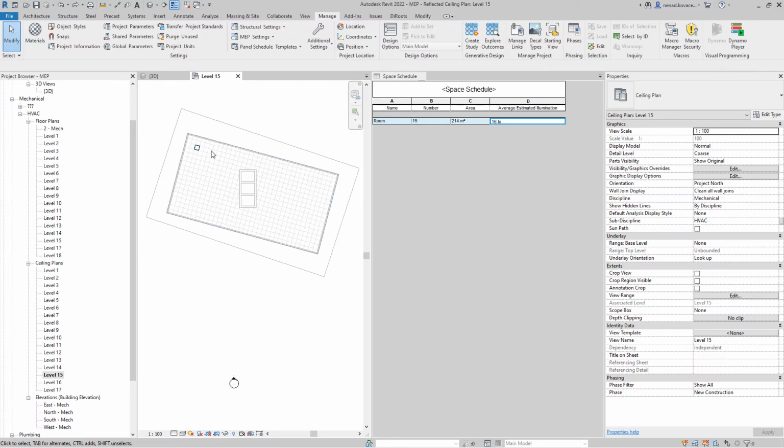Then when you divide what is left of the length and what the user required, Dynamo will know how many of those lighting features can generate, and then it will again divide what is required and what we have over here right now, and then it will just see how many rows we will need to have in order to be above what is required for illumination. So it is not a simple algorithm, but if you know some better way, you can let me know.